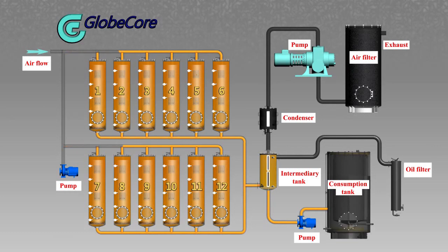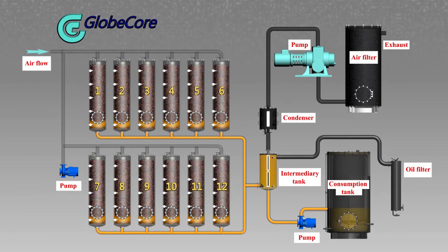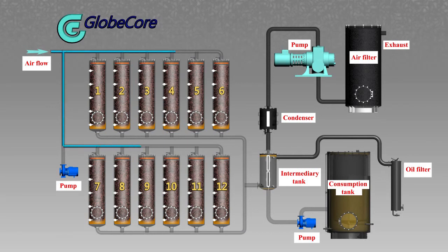The output pump drains the oil from the sorbent columns and puts it into the buffer tank. After the columns are completely drained, the vacuum pump starts. The vacuum pump creates airflow for the columns. Then the sorbent surface heater switches on. At this time, sorbent reactivation starts and absorbed oil decomposition products are extracted. When the reactivation process starts, the heating system switches off.